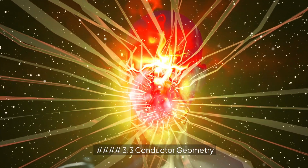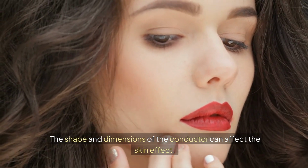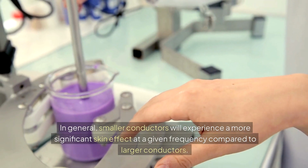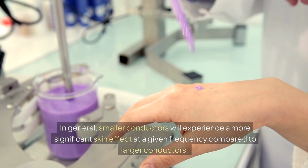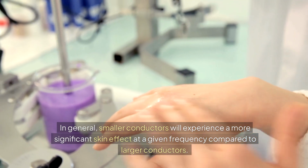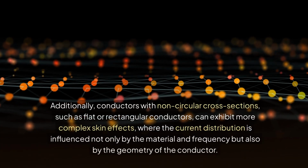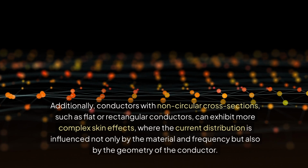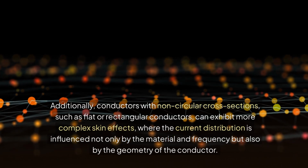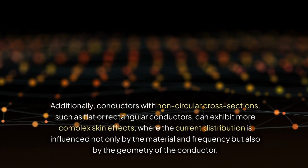Number 3.3 Conductor geometry. The shape and dimensions of the conductor can affect the skin effect. In general, smaller conductors will experience a more significant skin effect at a given frequency compared to larger conductors. Additionally, conductors with non-circular cross-sections, such as flat or rectangular conductors, can exhibit more complex skin effects, where the current distribution is influenced not only by the material and frequency but also by the geometry of the conductor.